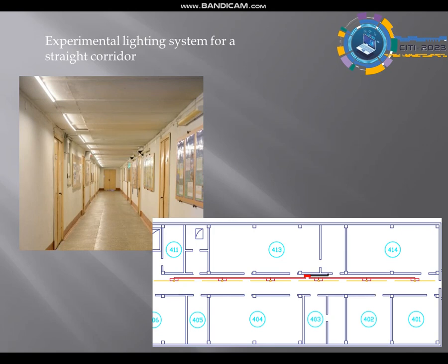The smooth switch on time depends on the following factors. When a person moves along the corridor, the time of the lamp brightness to increase should be no more than the time from the moment when the signal is received from the motion sensor to the moment the person approaches the illumination zone, and also not be less than the reaction and adaptation time of the human eye. Since these data are individual for each person, we conducted two field experiments.